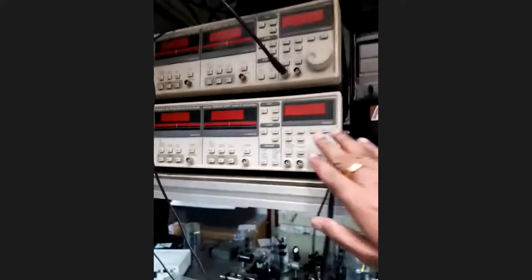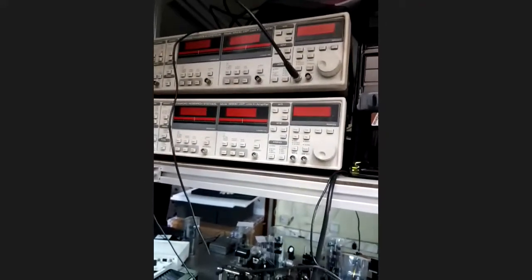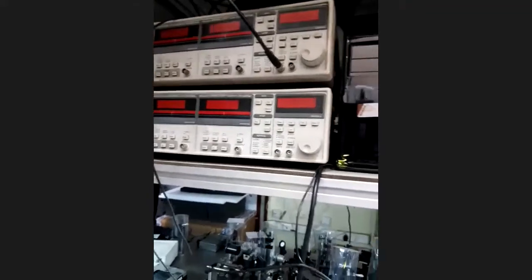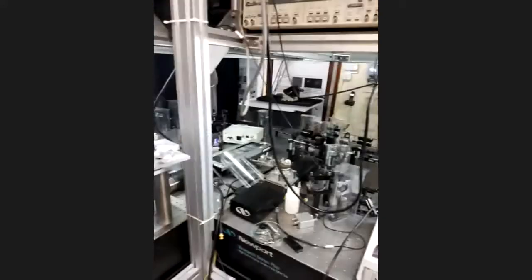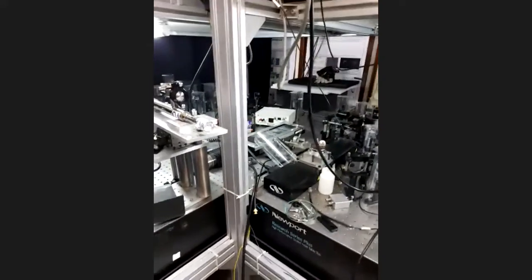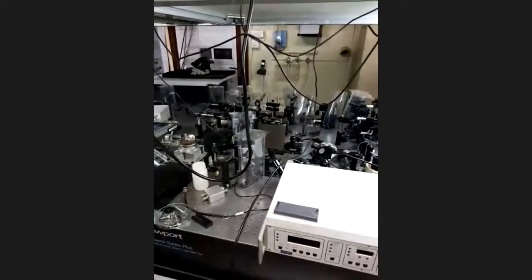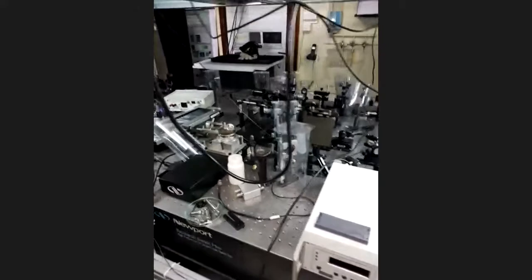So that reference can be given to a lock-in amplifier. A lock-in amplifier locks to that reference frequency and measures the signals coming only at that particular frequency. So I have a lot of light in the room. When actually we do the measurement, we switch off all the lights, and the only noise which comes out is because of the scattered light which is coming from the laser. Laser gets scattered at some points, and that scattered light also gives noise.